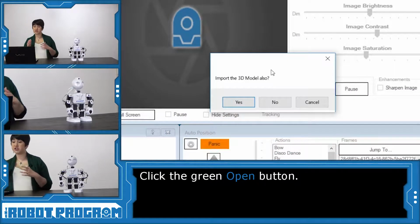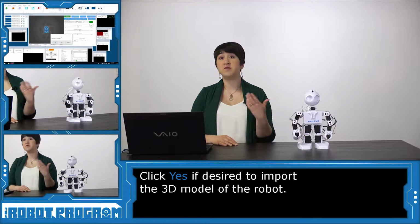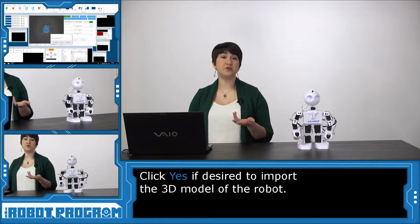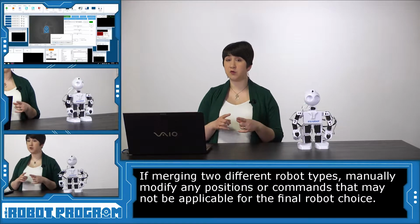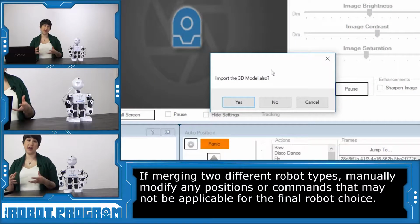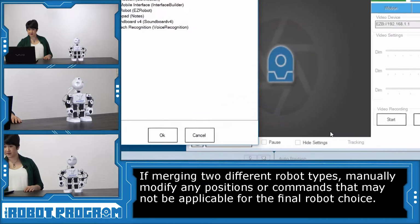And it asks if I want to import the 3D model also. Since I'm importing a JD project to a JD project, the model will be of JD, so that's okay. If you're bringing in a JD project to a Roly project, you can choose whether or not to import the model. Remember that if you're merging two different robot projects, you'll have to update some of the auto position commands or some of the other features that maybe you don't have on your new robot. So you have to remember to go in and update your project yourself. So I'm going to say yes.